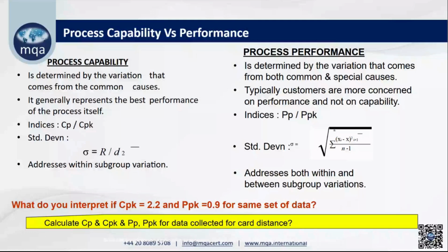See, I'll tell you an example. Like I told you, pilot production and regular production. We calculate capability for pilot production also. Pilot production means we are making 50 parts, and we calculate process capability on those 50 parts. Mass production means 5,000 pieces per week or per month, and we calculate PPK. So in that, the sample size is very limited, but it will give us the average. Understood?